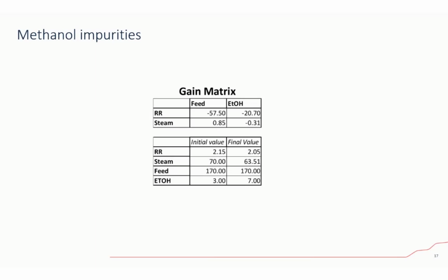Many times there's talk about using automated step testing, which is good for some of these simple columns. But is this good for these complex columns also? What is your take on that? Well, when you use automated step testing, there is one thing that you need to always consider: the steps need to be held for a time that is as close as possible to the time to steady state of the process.